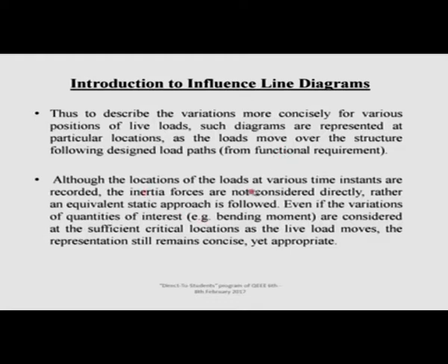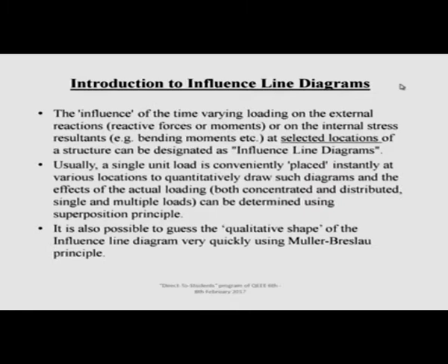Although the locations of the loads at various time instants are recorded, the inertia forces are not considered. I have just explained that it is in terms of an equivalent static load, and our treatment is fully static. Now, come straightaway to the introduction of influence line.